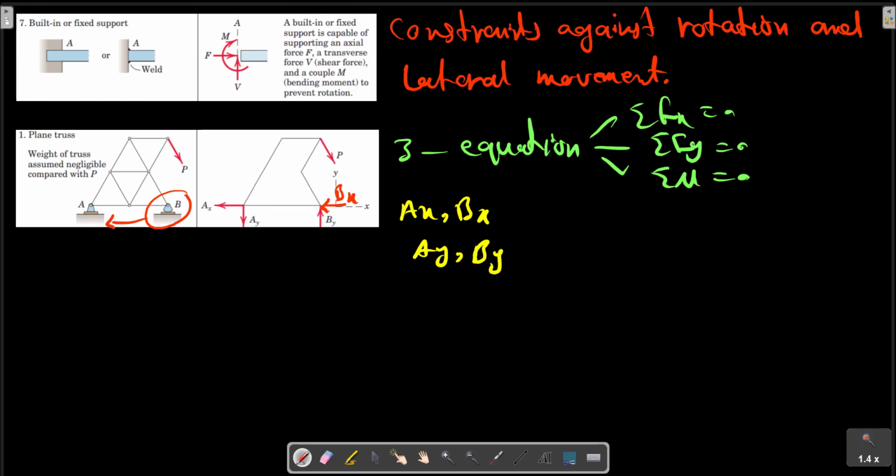In this case, these two components of force would be dependent on the deformation of the members of the truss as influenced by their corresponding stiffness properties. The horizontal reactions Ax and Bx would also depend on any initial deformation required to fit the dimensions of the structure to those of the foundation between A and B. Thus, we cannot determine Ax and Bx by a rigid body analysis.